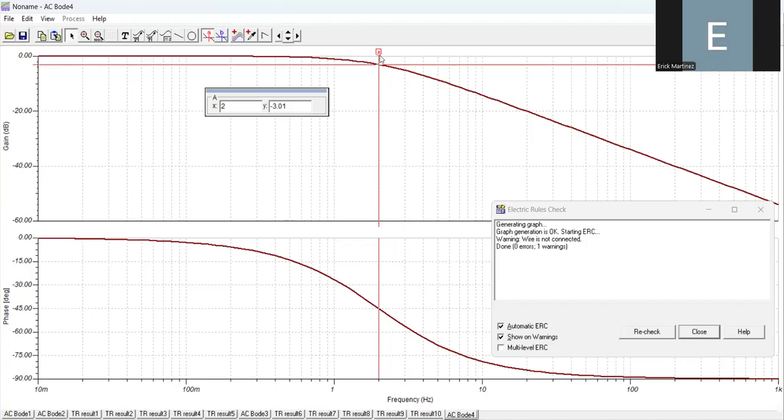So beginning from this point, we can see a greater decay in the output voltage compared to the input voltage because we're increasing the negative decibels of the filter. Remember that the negative decibels are associated with a lower amplitude in the output voltage compared to the input voltage. And this is the region that you need to analyze.